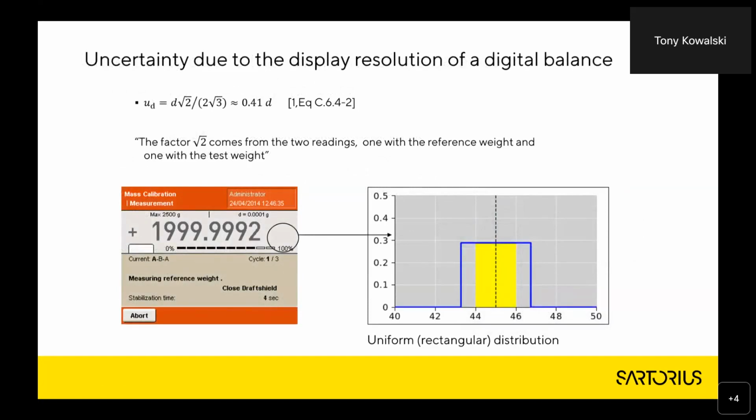So, there's always a slight error on a display resolution, because although the comparator is showing a value of 4 decimal places, there is an invisible decimal place, the internal resolution. So for that to be a 2, this value in the next decimal place has to be below 5.